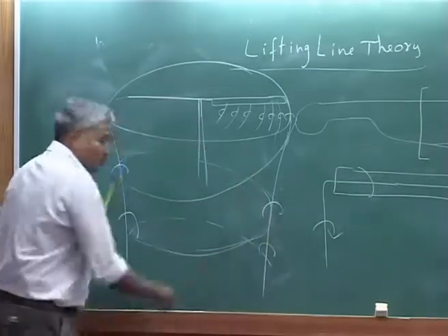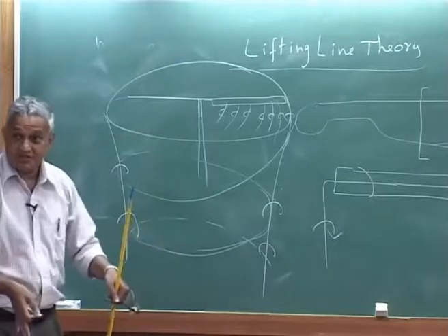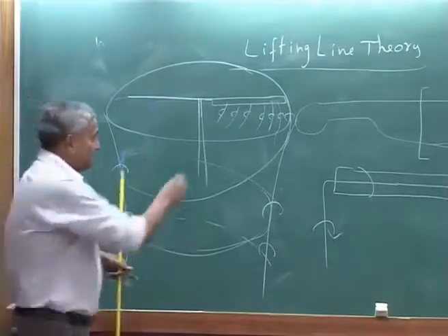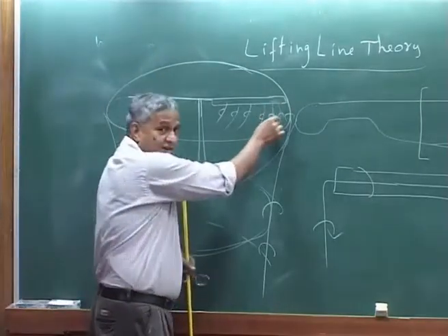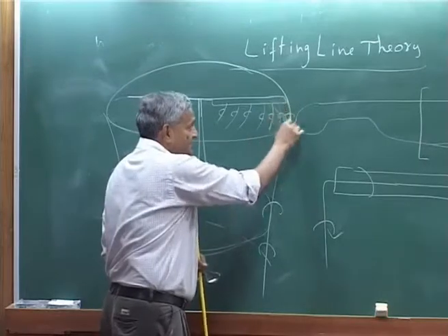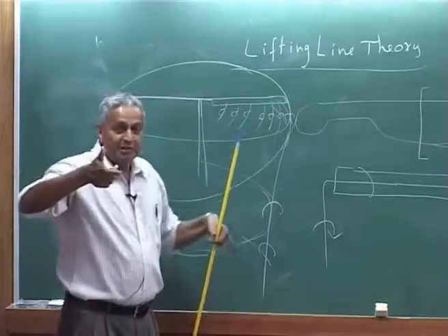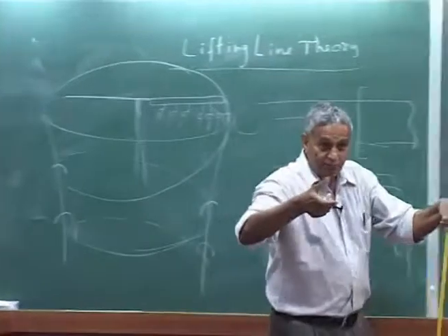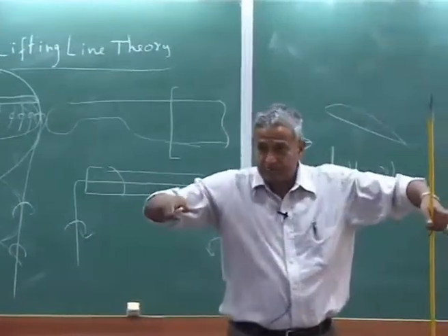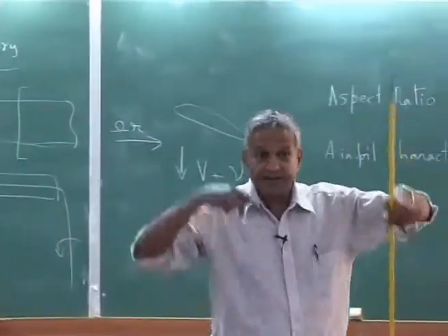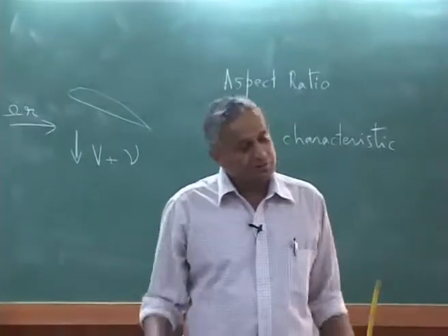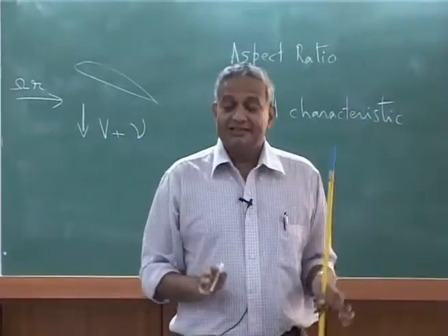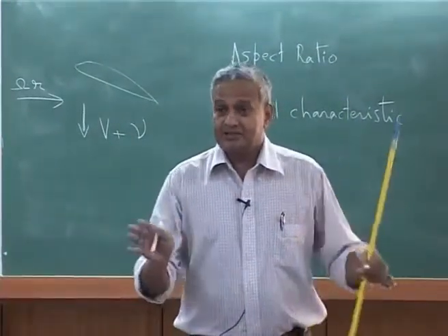So, like that this will go, a vortex sheet, and what will happen is initially they will start as a sheet, suddenly they will all bunch up and become a strong tip vortex, because you know that strong tip vortex and how that is convected down. That means you have to take a structure of that, that is the wake structure.